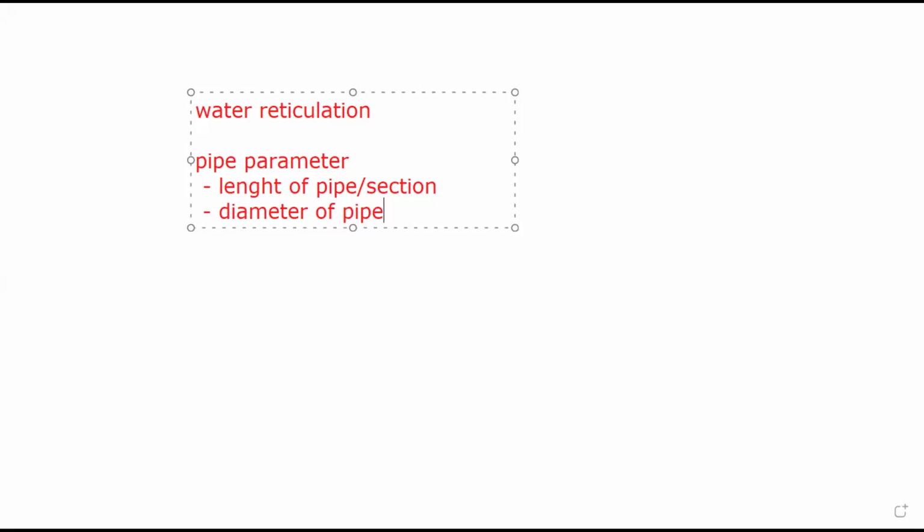Remember, I said there are 4 of them. So you must ask yourself, what is the diameter of the pipe? Because the diameter of the pipe is key. If the pipe is undersized, water will not flow. I have seen consultants that design water reticulation systems and they spend millions. And wrong pipe, water will not flow. Why? Because the pipe is so small.